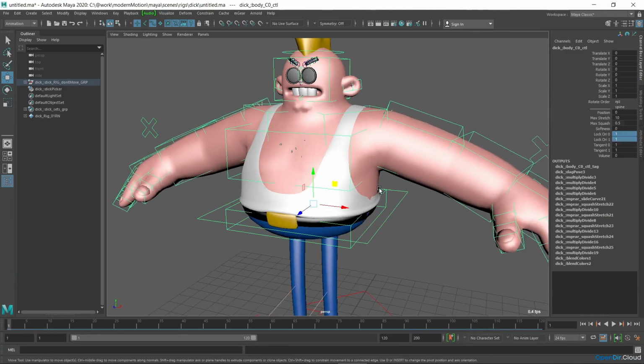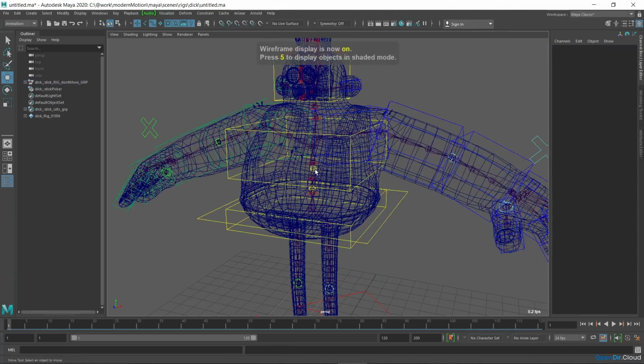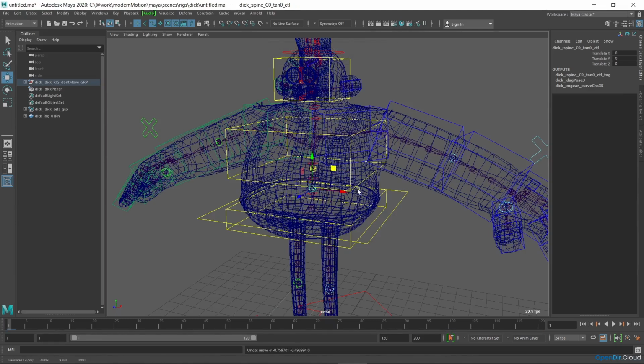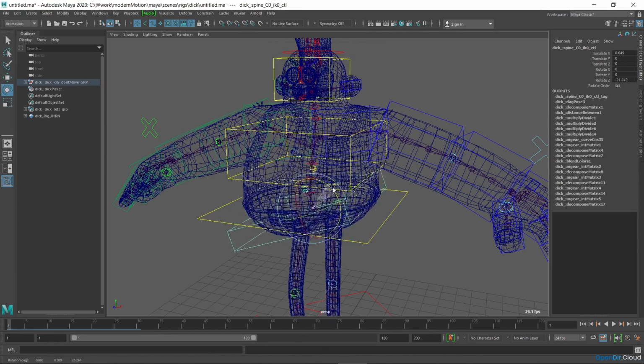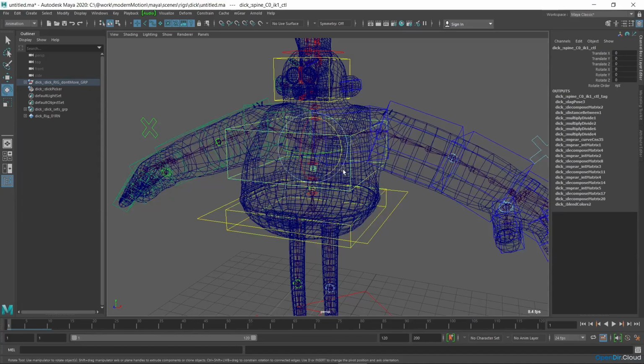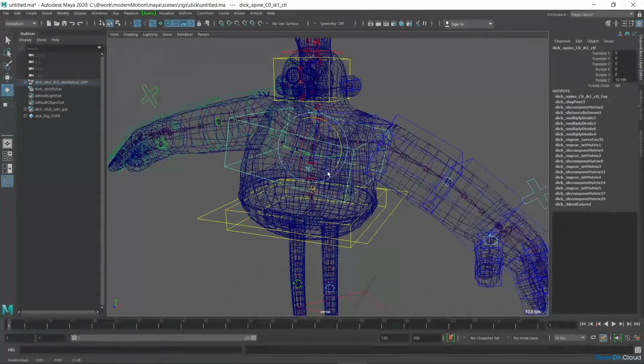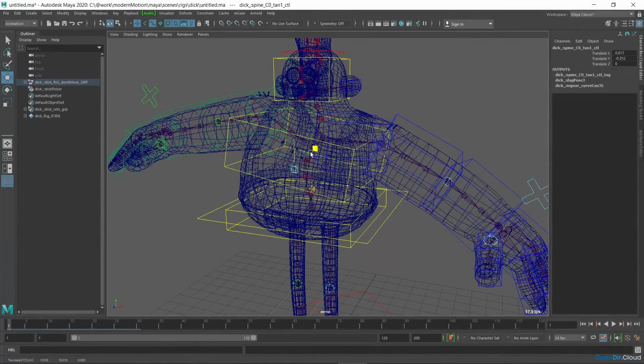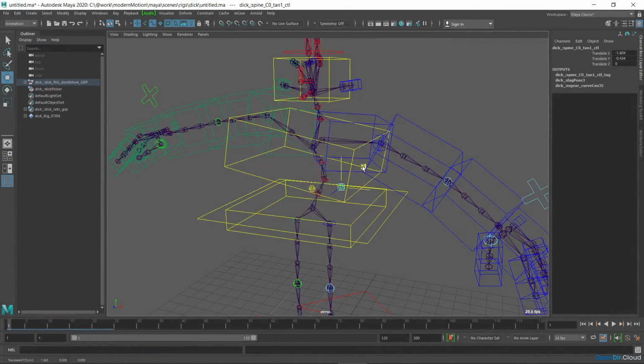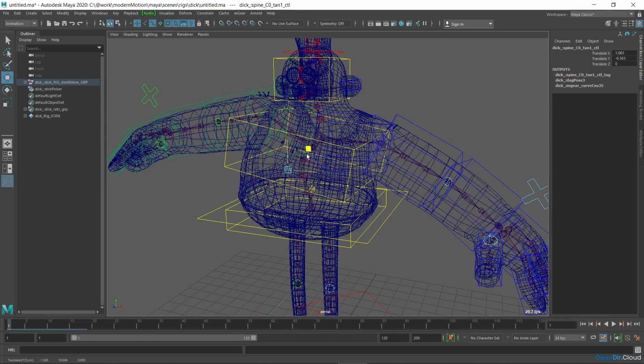There are also additional tangent controllers. These yellow spheres are designed to fine-tune the curvature of the spine. Each is the child of the corresponding chest or pelvis IK controller, and also inherits their transformations. You can see how the controllers shift the joints, but due to automatic skinning, they have little effect on the geometry. This can be fixed later, during the skinning correction phase.